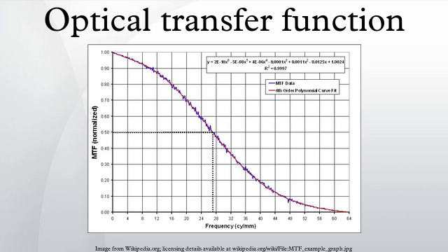The only theoretically correct way to interpolate or downconvert is by use of a steep low-pass spatial filter, realized by convolution with a two-dimensional sin x/x weighting function, which requires powerful processing. In practice, various mathematical approximations to this are used to reduce the processing requirement. These approximations are now implemented widely in video editing systems and in image processing programs such as Photoshop.